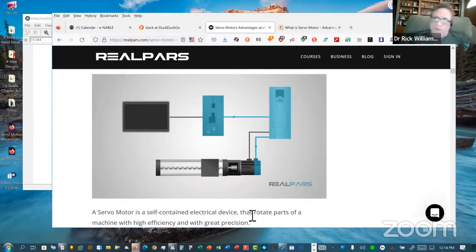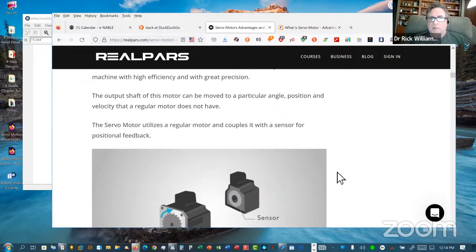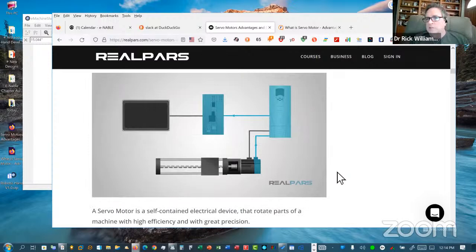We have a couple of devices here that use linear actuators on the hands, because they have a lot more lift, rather than the servos, where you're basically dealing in ounces. With linear actuators, even the smaller ones, you can get pound torque out of them, a lot of power. Not probably as much as we're getting with our motors, just because of the size differential. But linear actuators are extraordinarily good, though a little on the expensive side.